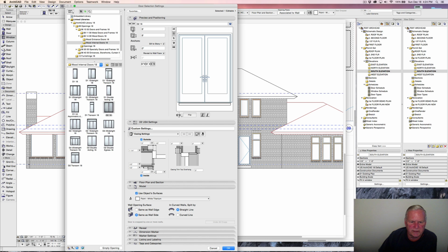If we look at all of our settings here, the margin overhang there at 1/4 inch, casings all at 2, jamb thickness there 1/2 inch, maybe correct, or could be 3/4, but that's fine for the moment. That's all set correctly. Threshold extended both sides. We've got the sill type here. Slip in depth, that's just how far it slides in under. We're going to change the pitch to 3 degrees. This 1 49/64, I think we'll just make that 2 inches. And I think for this thickness here, we'll make that 4 inches.